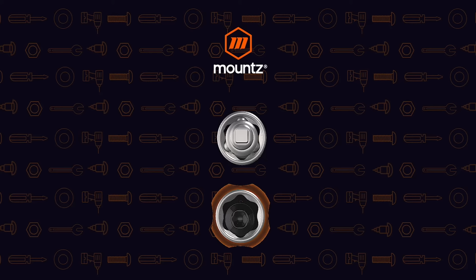That main housing contains a larger ball bearing that also has a thrust washer on it, and that then is compressing the spring. So this gives us a really nice and smooth operation as far as the torquing is concerned.